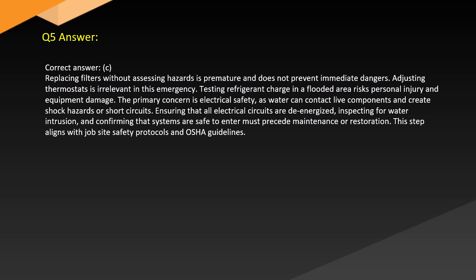Answer. Correct answer. C. Replacing filters without assessing hazards is premature and does not prevent immediate dangers. Adjusting thermostats is irrelevant in this emergency. Testing refrigerant charge in a flooded area risks personal injury and equipment damage. The primary concern is electrical safety, as water can contact live components and create shock hazards or short circuits. Ensuring that all electrical circuits are de-energized, inspecting for intrusion, and confirming that systems are safe to enter must precede maintenance or restoration. This step aligns with job site safety protocols and OSHA guidelines.